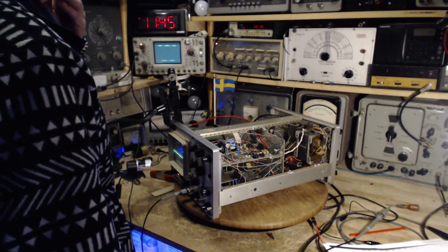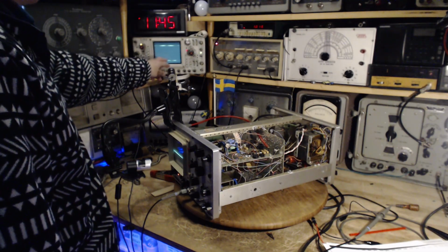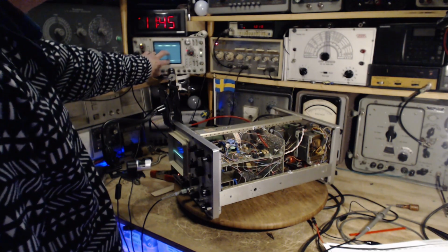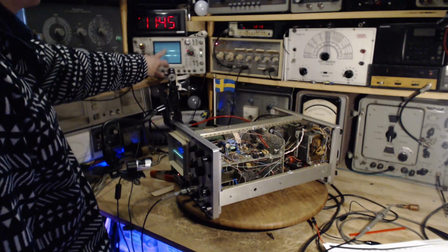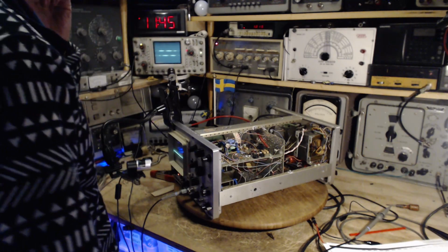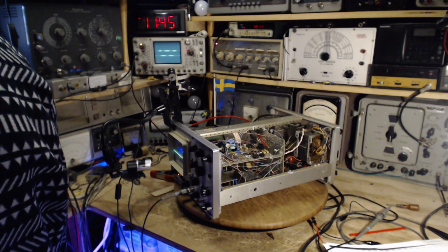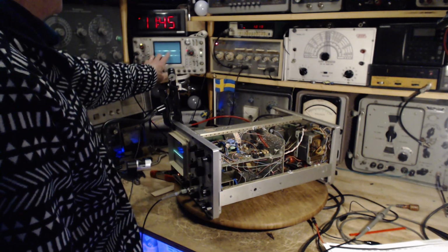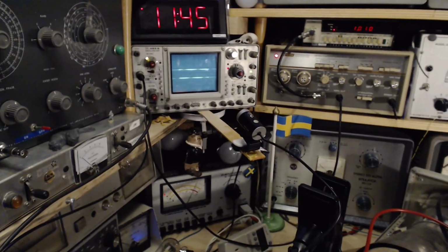So where are we here? So we're looking at 0.5 volts per division. So we're looking at like 1 volt should be down here. So we're way high. So I'm just going to put in a 10 dB pad. Very close now. Let me switch to that camera. I can't. That camera's not available right now, so that's okay. So I'm just going to adjust this until it's 1 volt. Come on over here. This is better. This will do it. Look at that.